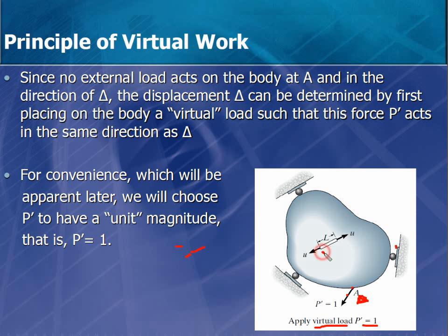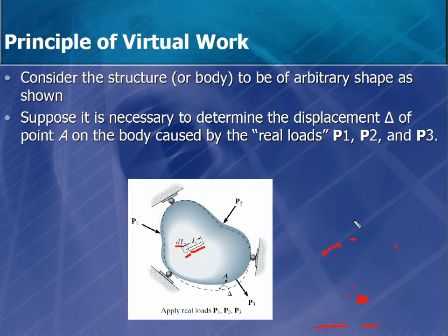This is the same element. Now the u here is the internal forces due to the virtual load. So the first time, when we had the external loads, those external loads are going to create deformation on the body. That's going to be dl.